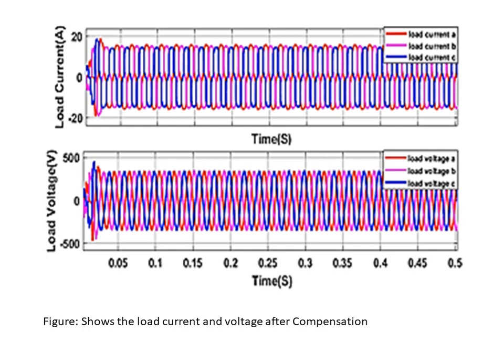Since there is non-linear load present in the system, this load will have some harmonics present. So it is highly impossible to have a pure sinusoidal voltage and current across the load, since it is non-linear and has a reactive power load. The main aim of this Dstatcom is to reduce the harmonics at the source side. So a few of the harmonics will be present across the load.